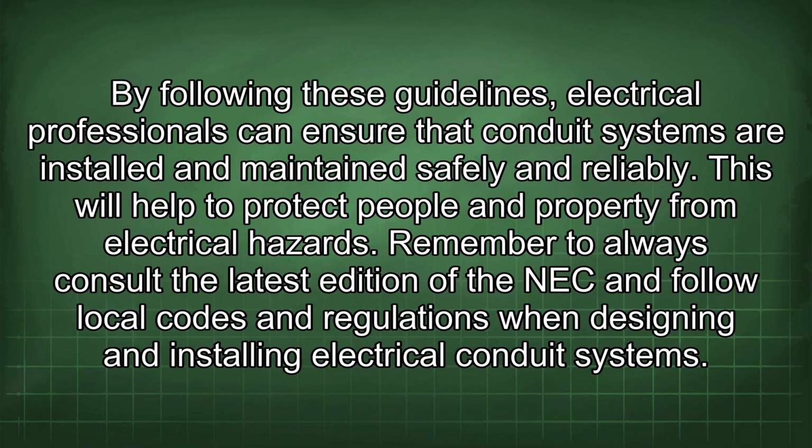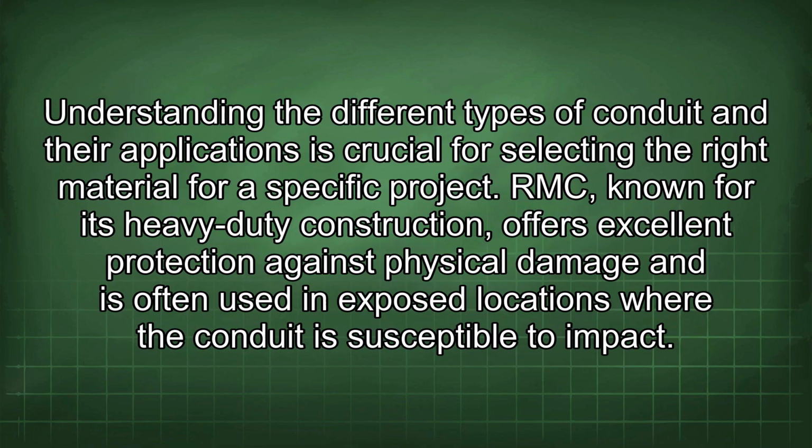electrical conduit systems. Understanding the different types of conduit and their applications is crucial for selecting the right material for a specific project. RMC, known for its heavy-duty construction, offers excellent protection against physical damage and is often used in exposed locations where the conduit is susceptible to impact.